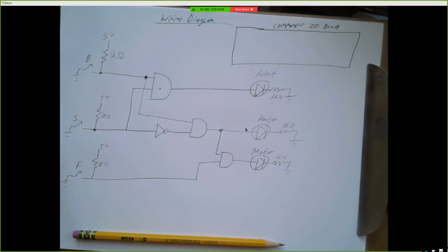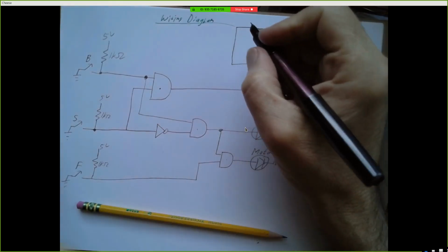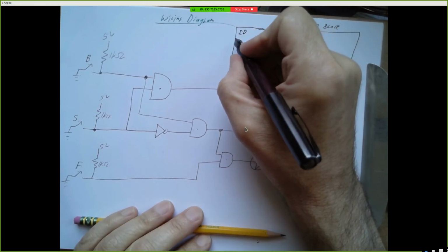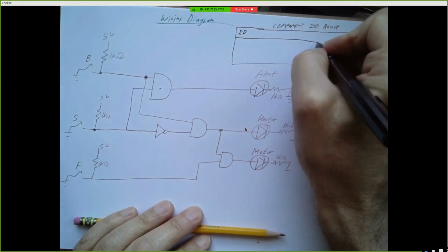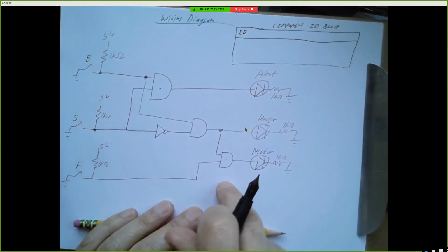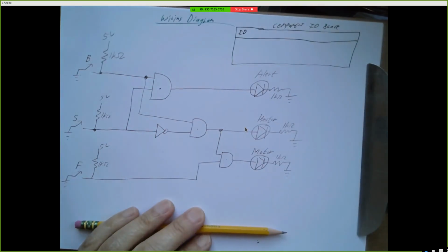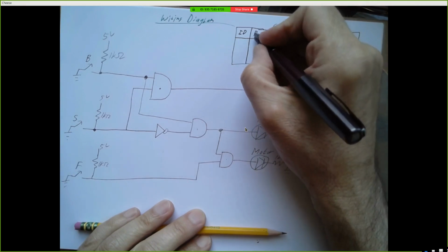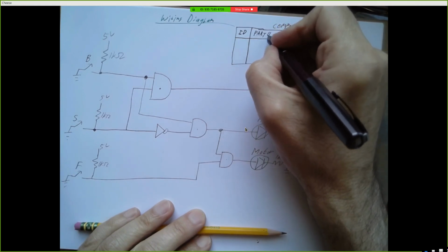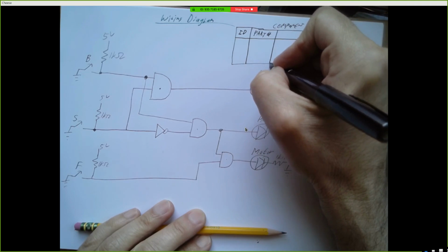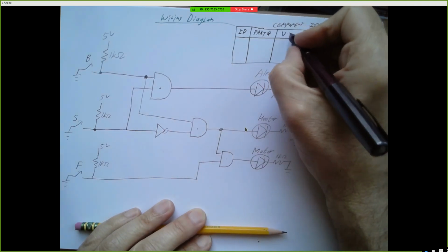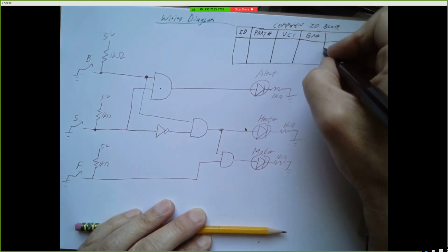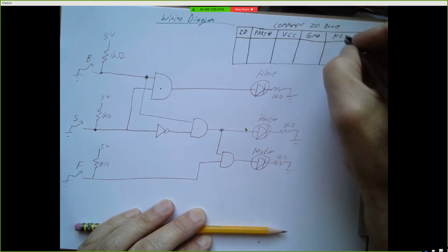Okay, typically goes in the upper right, and it's going to have an identification, and we're going to identify each of these logic gates using a symbol like U1 or U2. We're going to say what the part number is, 74HC04, etc. We're going to say where we connect to power, where we connect to ground, and it's nice to say where do we not connect to anything.